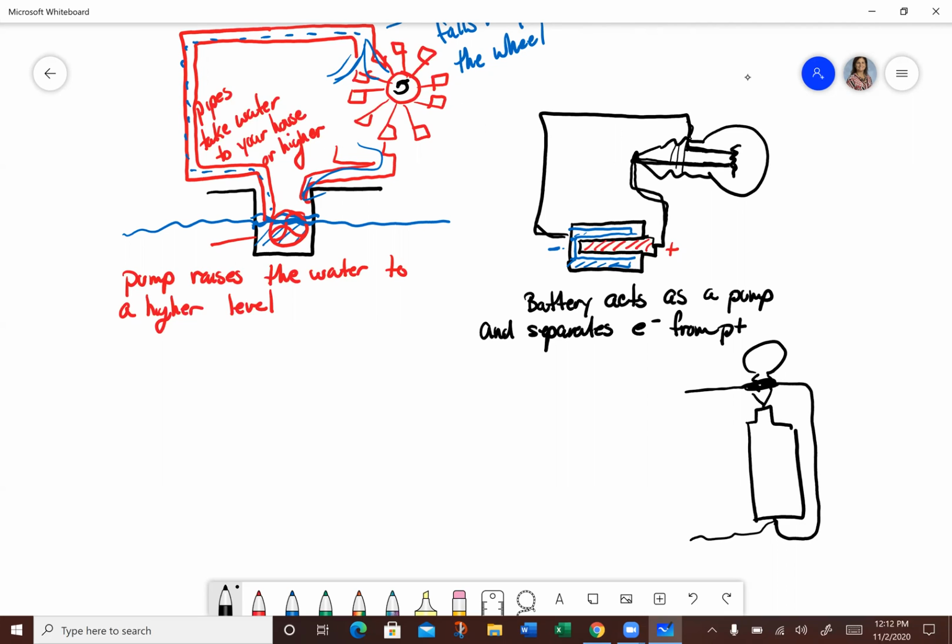And the electrons will come out of the negative, go through here, go into the side, up through the filament, back out the bottom into where the positives are. So if you bypass that and you allow this wire to connect directly into here, that is our short circuit. And that's what was causing a lot of your batteries to become warm.